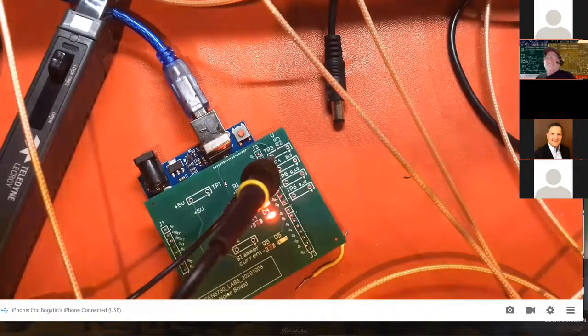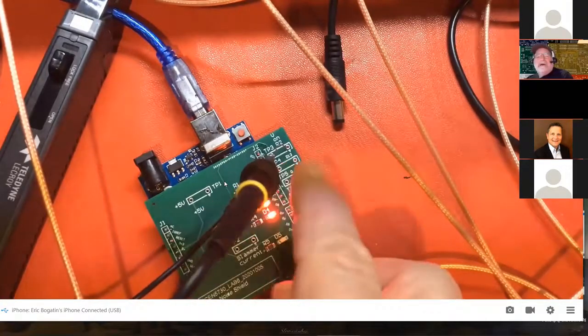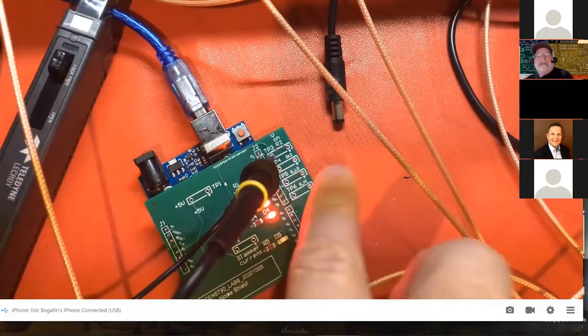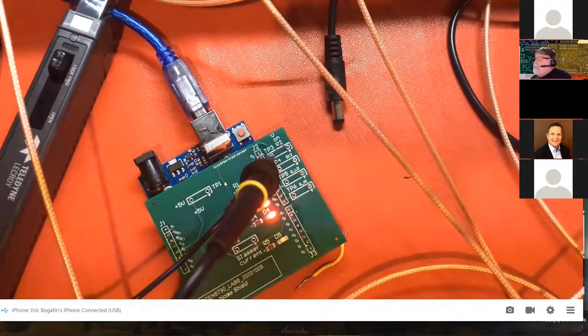Okay, good. And another question regarding probing with the passive probe is what would be the improvement I could expect if I went to the trouble of attaching a coaxial connector to my probe tip? Very good. Yeah. So again, we have another webinar we've done recently where we actually compared the bandwidth of a 10x probe in the 3 different configurations. The case of a really long lead, the little spring tip, and then into a direct coax connection. And generally, you get the maximum bandwidth when you have the coax connection.